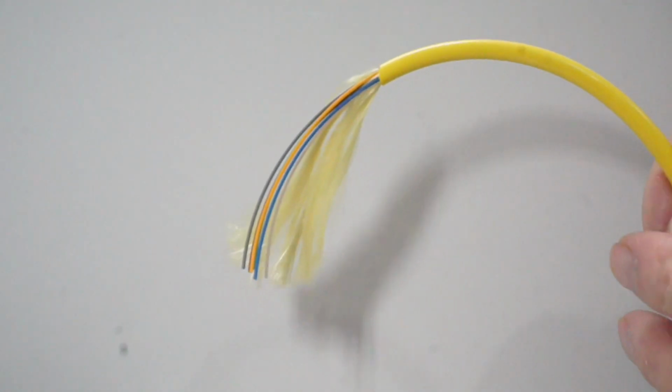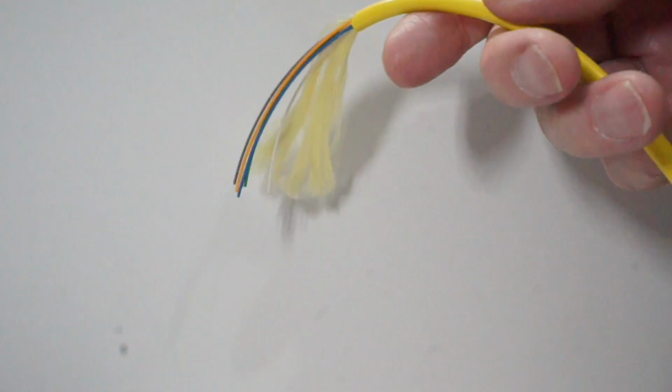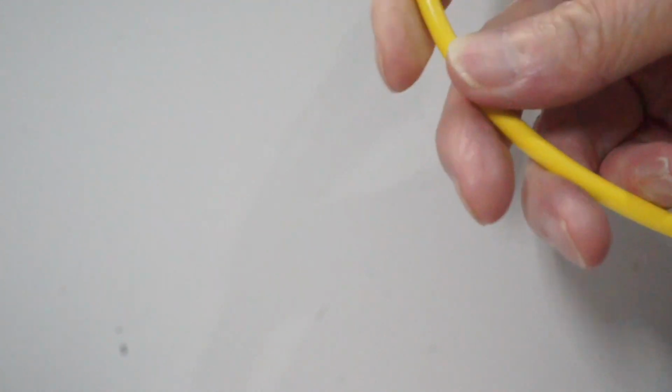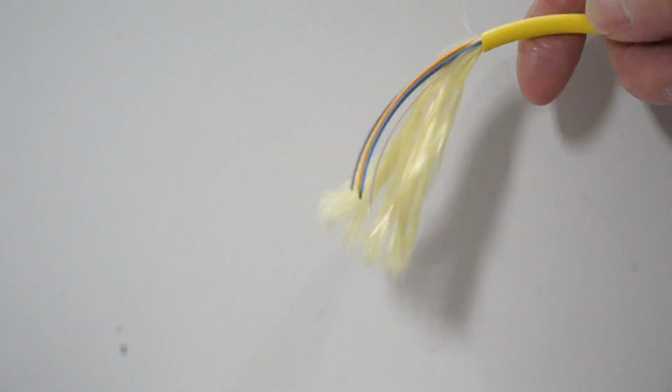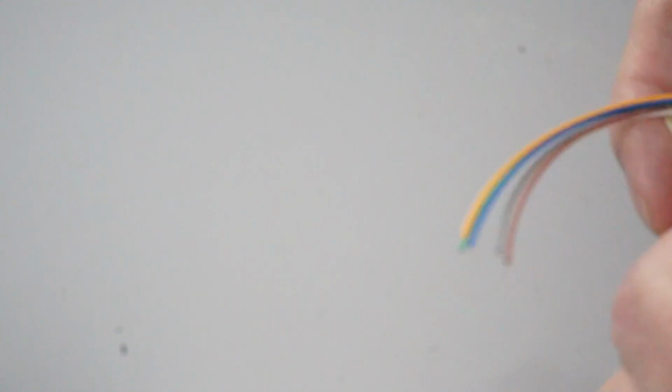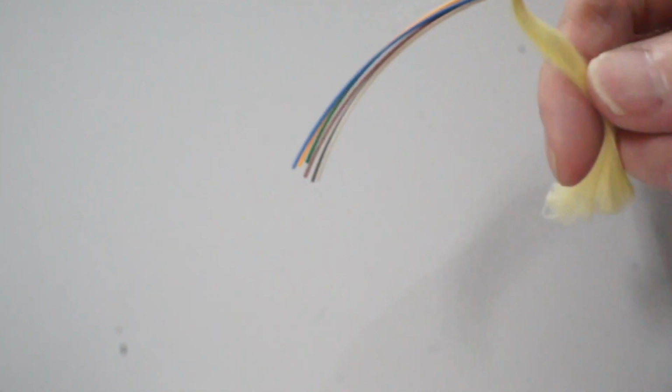And so next in this section, let's take a look at some fiber optic cable and figure out what the heck's going on with it. Taking a close-up view, here is some OFNR cable, fiber optic cable. It says on the jacket OFNR, which means that it's optical fiber, it is non-conductive, there's no metal components on the inside, and it's suitable for use in riser applications.